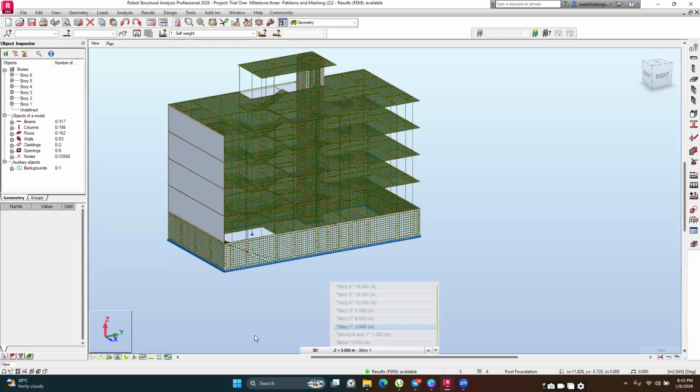Hello, Captain. Hello, engineer. If we have errors and the analysis is running, are we going to pause or stop so that we can correct the errors in the mesh? It depends on the nature of the error. If it's the incoherent mesh and it's just a small portion, you could assume it and proceed with the analysis. If it's the instability errors, just stop the analysis completely and go and revise your model and ensure that you've modeled correctly. Is that okay?